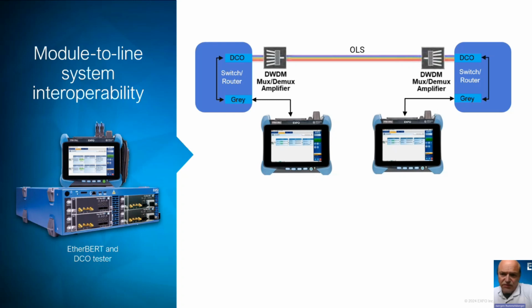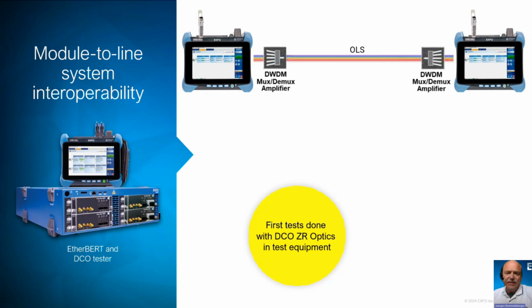And this was also the case with the 400G pluggables. So that means the initial test must be performed with the current transceivers plugged into the test equipment, depending on which channel, if not all, has to be tested. The transceiver then first must be configured accordingly, which means the application selection, the grid, the TX power, and also the wavelength or the channel.